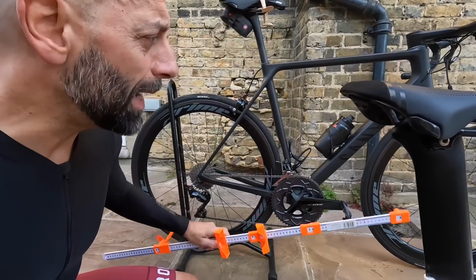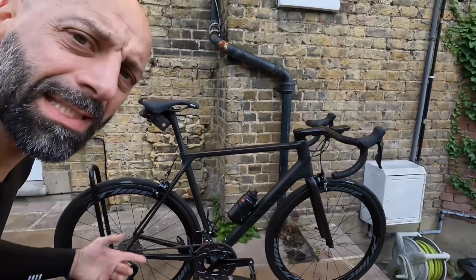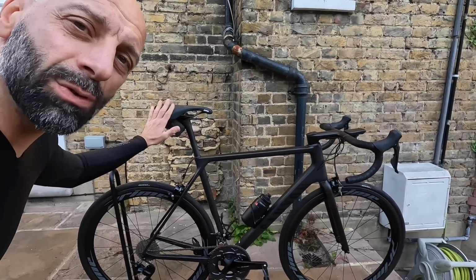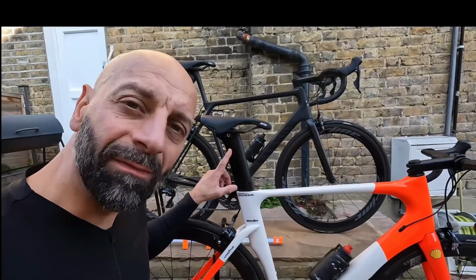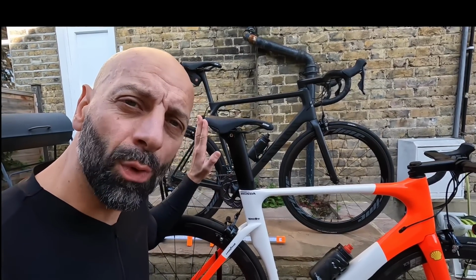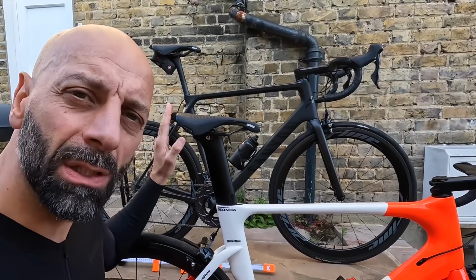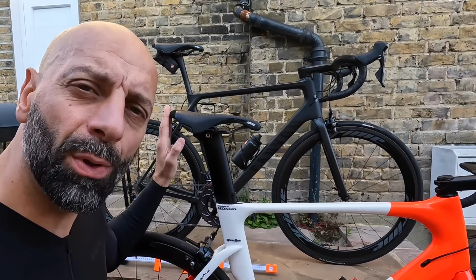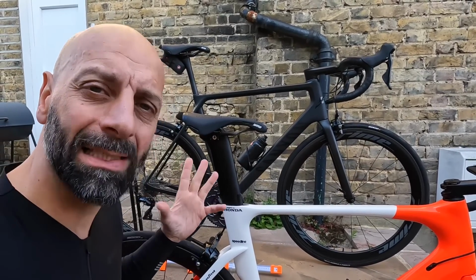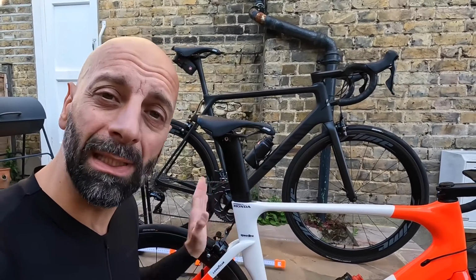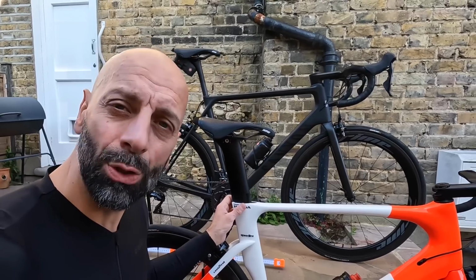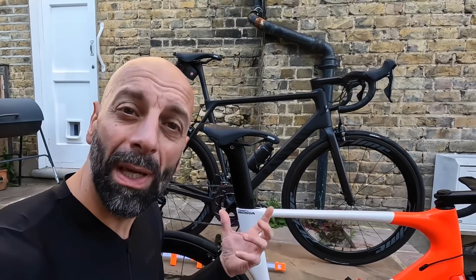If you look at these two bikes, the saddle on the Canyon seems almost centered on the seat post, while the saddle on the Velobuild is pushed all the way forward, almost at the end of the rails of the seat post, to put me in the exact same position. And this is down to the slightly different geometry, so this is a very important element, the angle of the seat tube, that you need to consider, because it will have a major effect on the way you ride the bike.